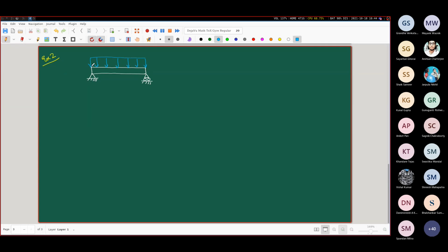There's going to be one vertical unknown here, one horizontal unknown here, and one vertical unknown here. There is not going to be any horizontal unknown here because the way that this structure has been presented, there is no resistance against the horizontal movement of this end. And since there is no resistance against the horizontal movement of this end, there is no reaction force also here, in the horizontal direction. It is only in the vertical direction that you are going to have some kind of a reaction force. Okay, so the strength of this thing is W, and it is in the unit of Newton per meter.